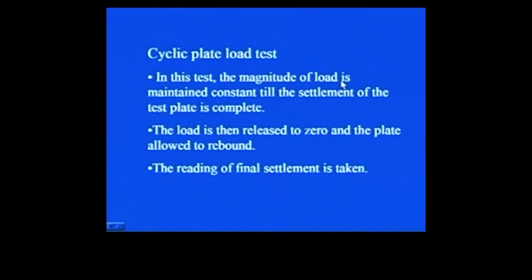plate is complete. That means that only when further settlement of the test plate is not occurring can you increase or decrease the load in case of loading or unloading respectively, but till the point the test plate is settling, you have to maintain the load on the test plate. The load is then released to 0 and the plate allowed to rebound.